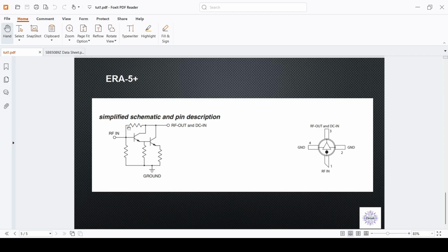And also they create the matching because you can just simply say, I create the matching by having an explicit 50 ohm resistor, or make the equivalent when I look at the base to be 50 ohm. So across all the frequency range, because it's a resistor, its impedance does not change. I just look at the 50 ohm, right?